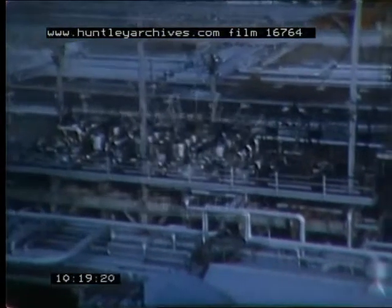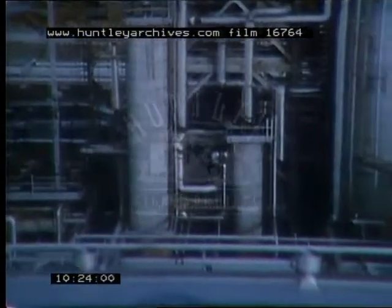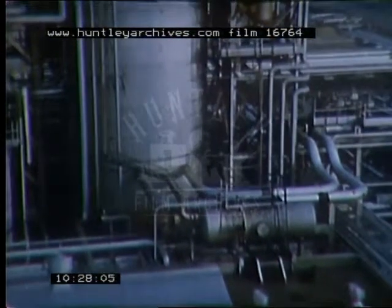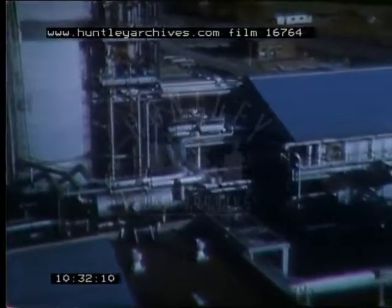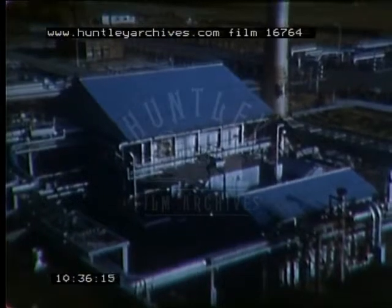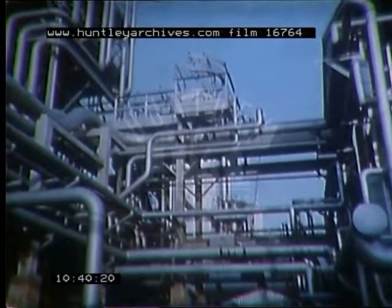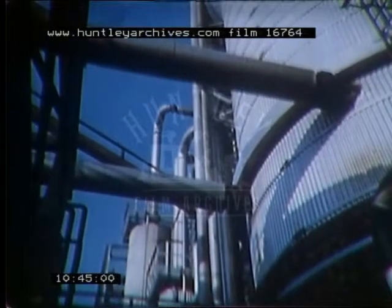The residue is fed through the heat exchangers, where it is warmed by heat from the hot products of the unit. It is further heated to a high temperature in the atmospheric residue heater. It leaves the heater in several large pipes which carry the residue into the base of the main tower.